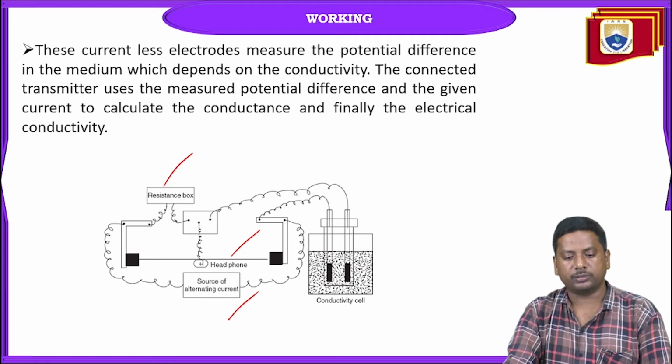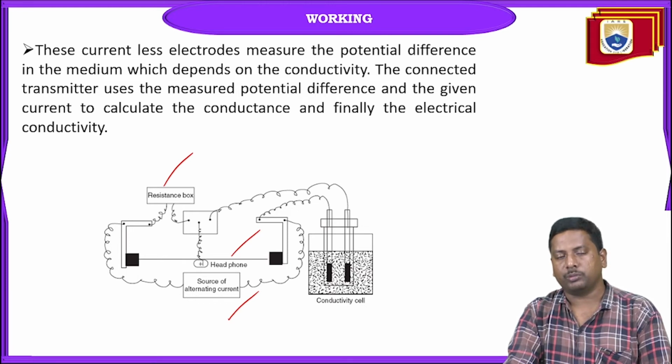Finally, the electrodes measure the potential difference. The potential difference takes place whenever charge transfer takes place. That means at one electrode oxidation takes place and at the other reduction takes place, and the resultant ions, anions, move towards the positive electrode, whereas cations move towards the negative electrode. Finally, it measures the conductivity because of the mobility of ions.